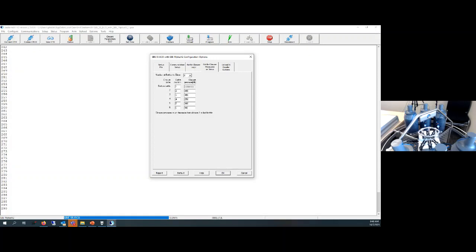Now, something that is typically best practice with water sampling is you want to hold your CTD package in place for at a minimum 60 seconds to allow the water in the bottle to equilibrate, to get rid of the impact of your profiler through the water. Unfortunately, because you're using autonomous bottle firing, you don't really have the option to do that here because you don't necessarily know when you're reaching these pressures without real-time feedback.